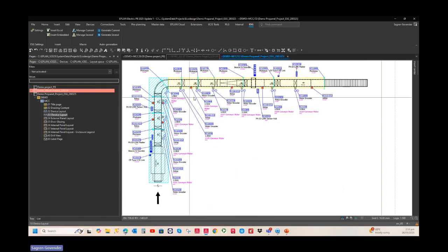And these drives are mounted on the field. They are distributed drives. This is a Siemens system. So there's Profinet. The drives are on Profinet. And there's also IO-Link modules along the conveyor here as well, with some devices connected to them.